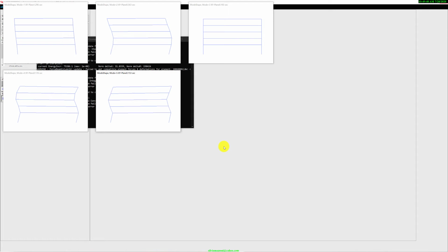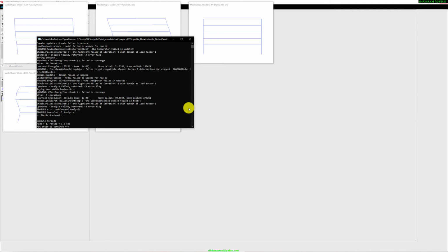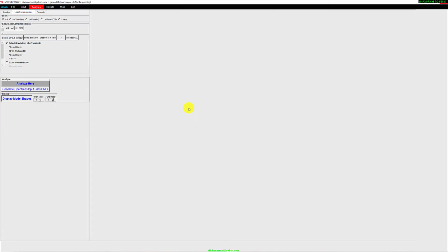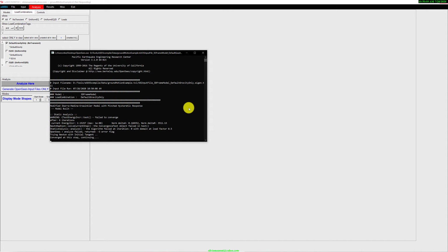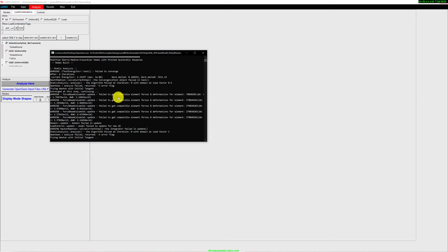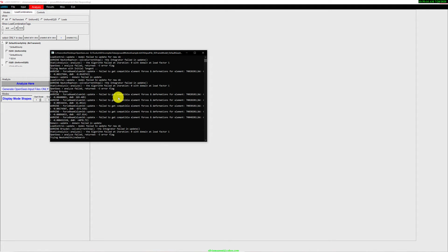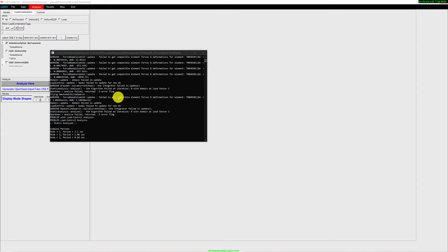But once it's applied gravity, then it's going to perform an eigenvalue analysis. And here are my 5 different modes. It's actually consistent with what I'm expecting. I believe this is probably axial, that it's hard to see here. And I'm happy with this. And go find your window and you press enter. Now it's going to go to the 3D model. Applying gravity. You can see the OpenSees analysis is trying to run. Maybe I should define a better section, or maybe my loads were too high.